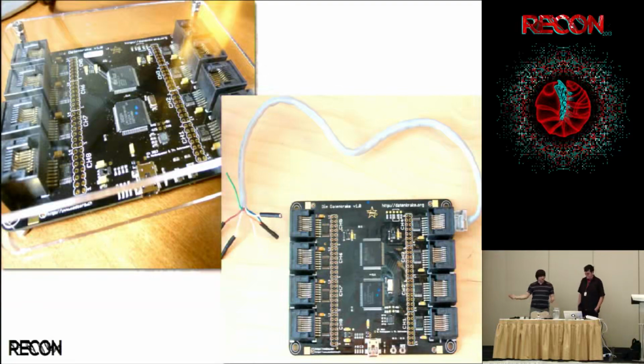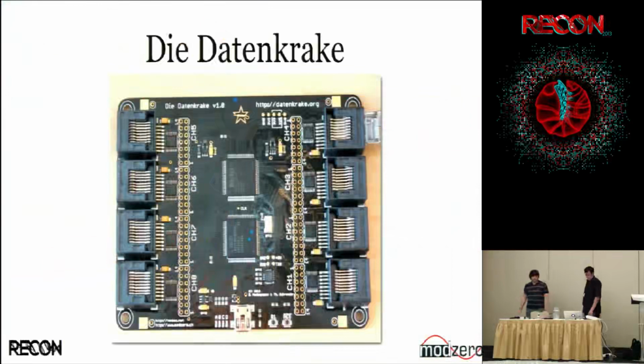So every port has, the other important thing is, we have 56 general purpose I/O at each of these RJ45 ports that you see on the sides. But we'll get into that. Just the 56: we have 56 GPIO because we have 8 ports and 6 pins that come out over these ports. You have 6 GPIO, and you also have VCC and ground, which means if you want to design a custom board, a little board that just connects over Ethernet, you can do it, and then you can do something crazy, do your own termination. Well, I wouldn't do LVDS.